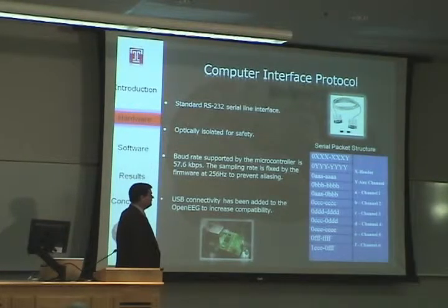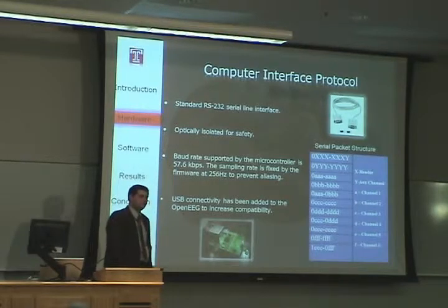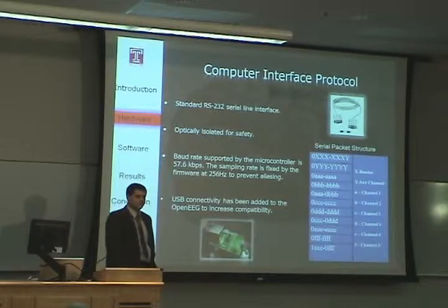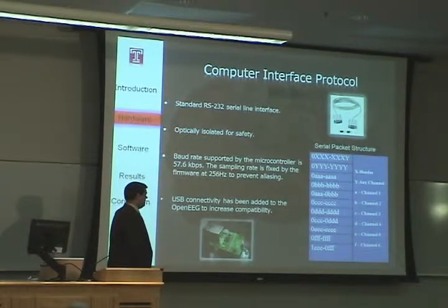Okay, the computer interface protocol is a standard RS-232 system. It's opto-isolated for safety concerns. And it also supports a baud rate of 57.6 kilobits per second. And this is well enough to support our 256 Hz sample rate.